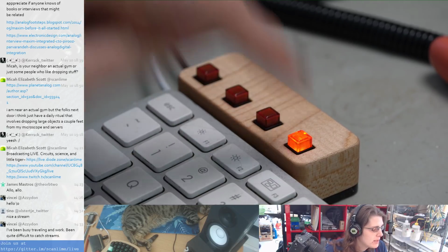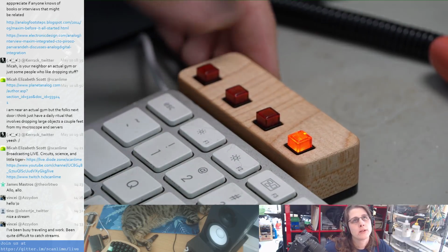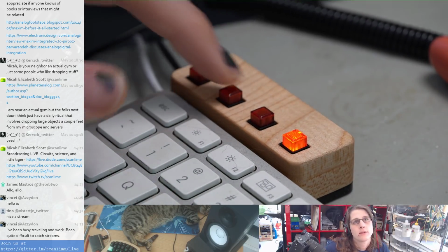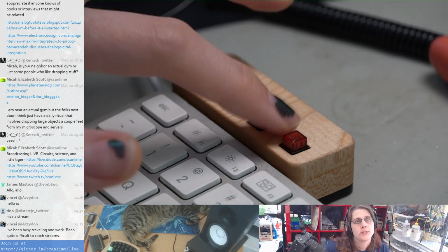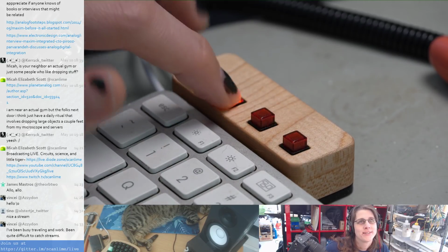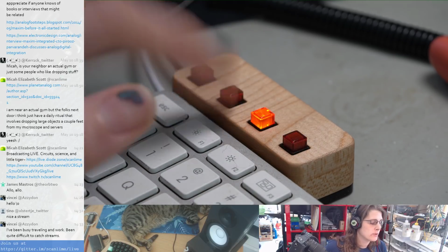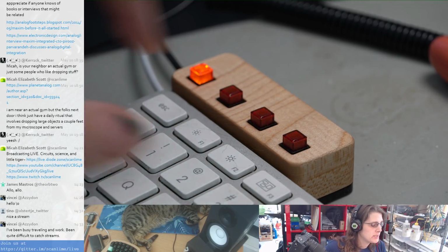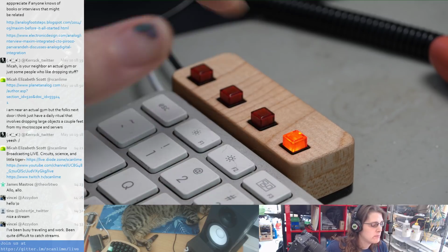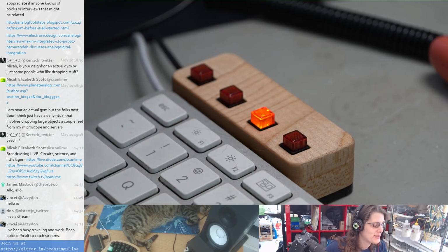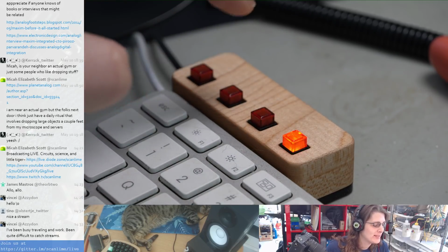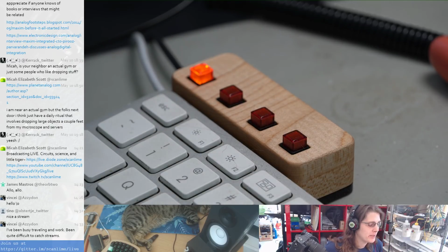I don't know, it's pretty satisfying. It has a nice smooth wood enclosure. Nice glow through these vintage LED buttons. The buttons originally had these fairly old school dim 3mm LEDs, and I didn't have any modern 3mm to replace it with, so I ended up taking some surface mount white LEDs and sticking them in there on some makeshift legs, and that seemed to work pretty well.